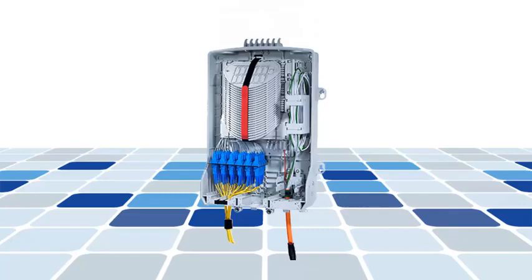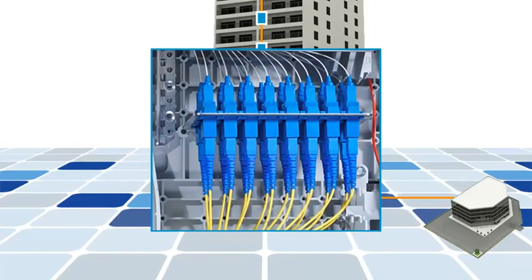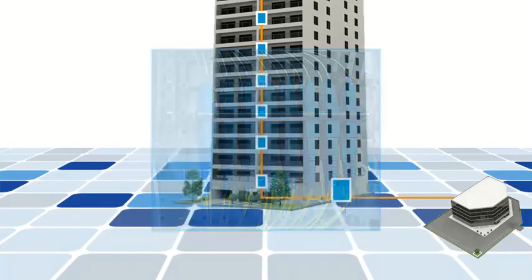In existing sites, it may be best to go for a hybrid solution because most brownfield MDUs have a congested building infrastructure. This means that fiber optic cables are pre-terminated or connectorized at one end and spliced at the other, with the least accessible or difficult end pre-terminated and the other side spliced in the field.